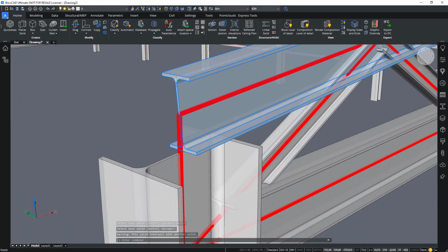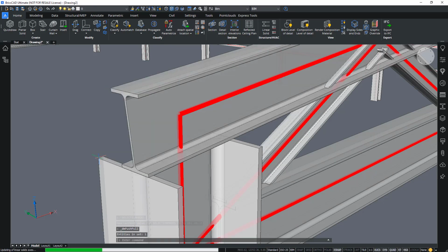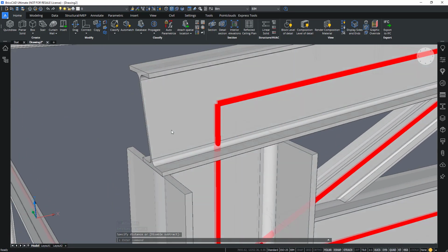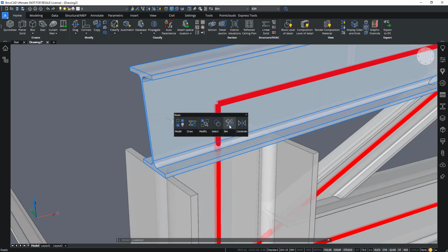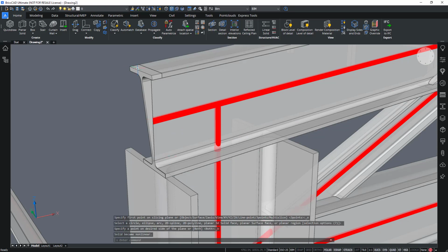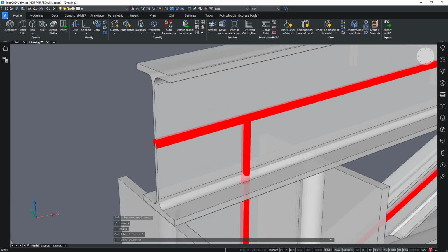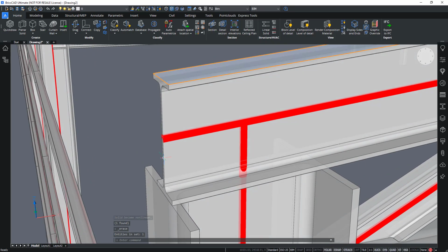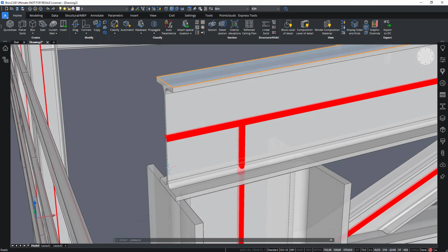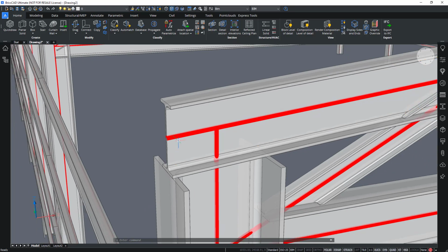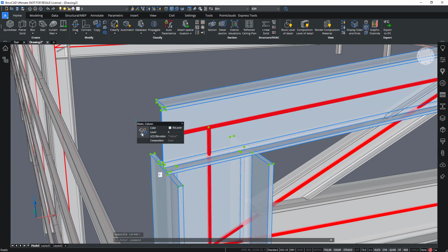And actually, I'm going to still edit this a bit, manipulate it a bit to, first of all, pull it all the way to this edge. And then to also slice it up. So the end is vertical, like this. Now you notice, because I did this manual manipulation of the end of this beam here, that my axis was recalculated. So the axis is no longer, well, it's connected to the beam, or to the column here, but also runs to the end. If you want, you can still fix this by simply using structural connect again.